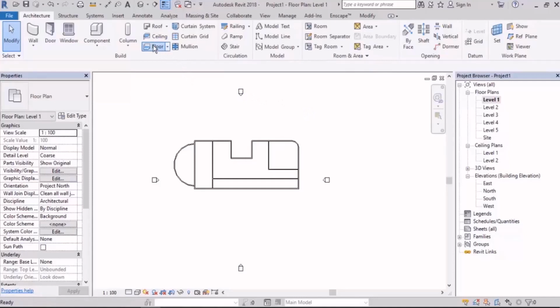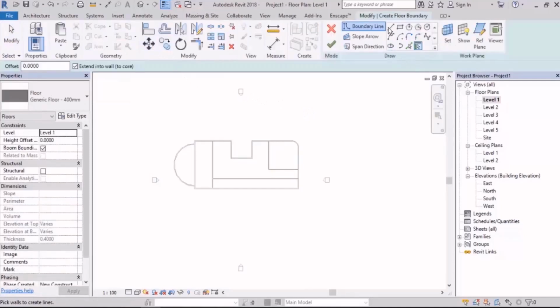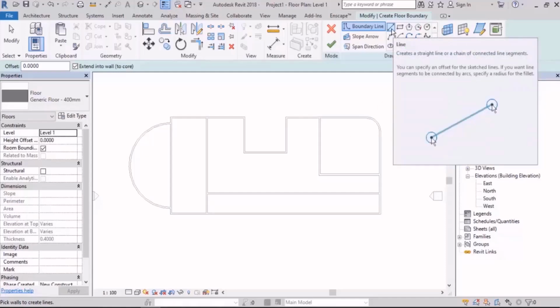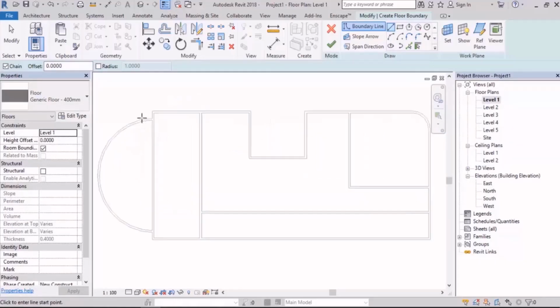Now let's start drawing. I activate the floor, and here I can see some tools that are a little like the tools in the wall, and I can draw my floor by using these. So I come here and draw the structural floor or the concrete floor that I set, it's 10 centimeters as a default. And just like I said, we don't want to change it now. We go based on the Revit default. So I pick the line here, which is straight, and start.